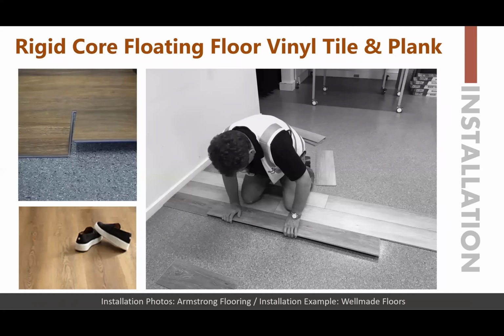There's not much of an installation method difference between SPC and WPC LVT, but there's an important distinction between what the installations are and how they are applied. For instance, an intended click-together LVT is similar for SPC and WPC, and if some adhesive is used, the installation should not fully adhere a floating floor. Typically, loose lay is intended not to have adhesive, but some installations may require a partial adherence in a commercial application. But again, if full adherence is required, the product should be changed to use a fully adhered installation. A non-click vinyl plank for a commercial installation does not click together as the edges are butted.